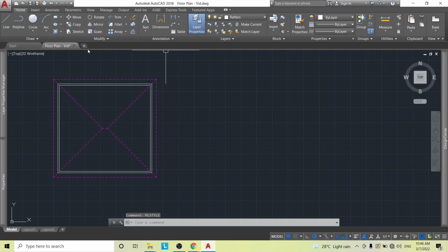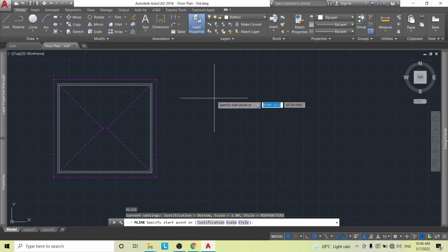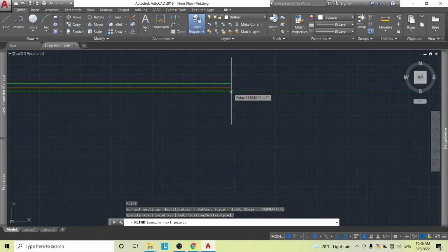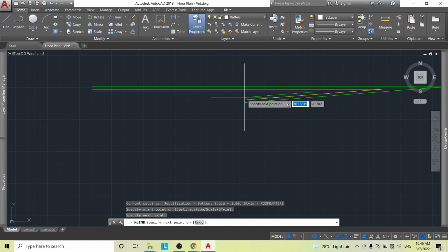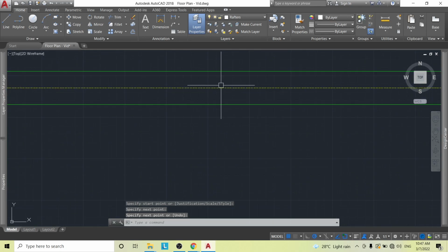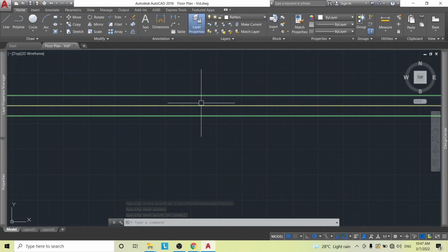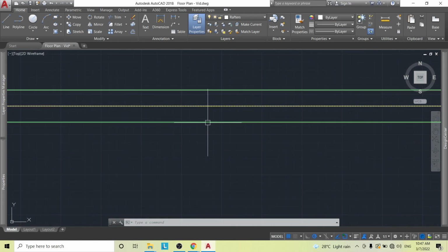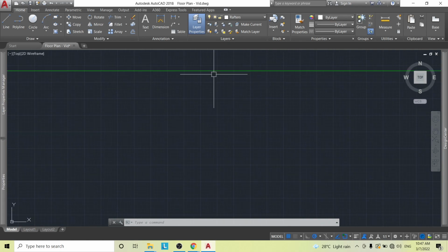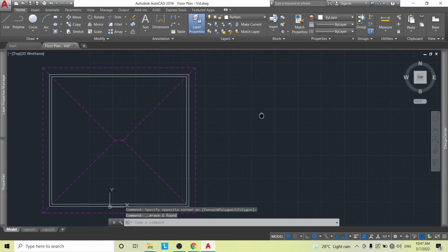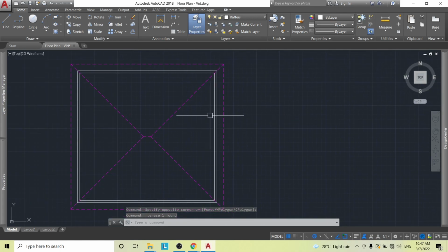All right, so now when we draw a line with a multi-line, we type ML, enter. The multi-line is going to show up like that. Three lines, there's one in the center. I notice it is the dash line that we designated. And then the ones on the end that are green are solid continuous lines. Okay, so those are the lines we need to use to do the rafters. So this is how we're going to do it really quickly.